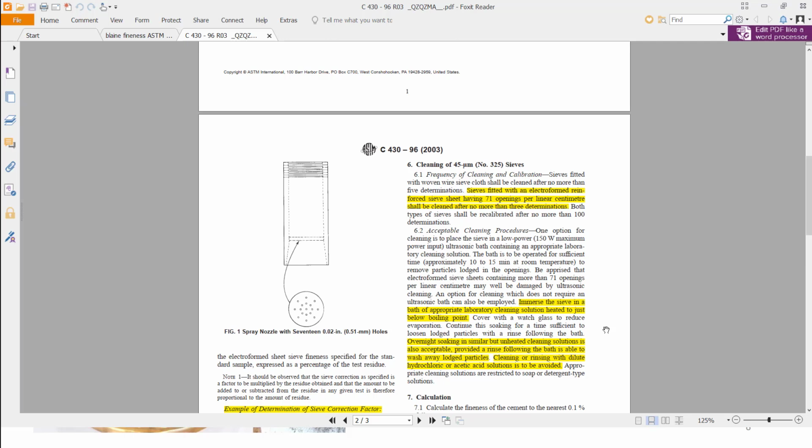On the other hand, you can perform the wet sieve method. You place a specimen on the sieve and use a jet of water that forces the particles to move through the openings of the sieve. After 10 to 15 minutes, you will get some residue retained on the sieve. You will calculate the weight after oven drying for 24 hours. In this way, you can calibrate your sieve.